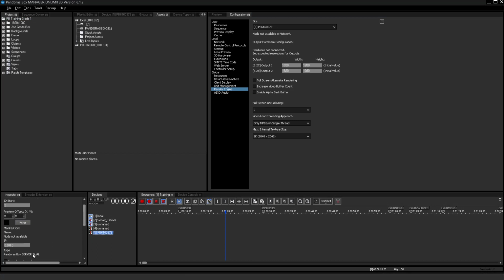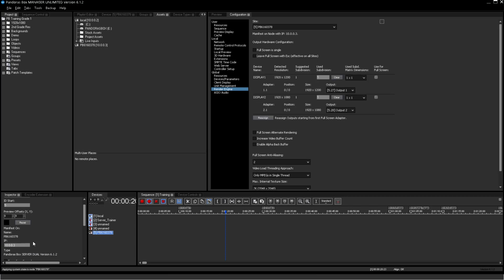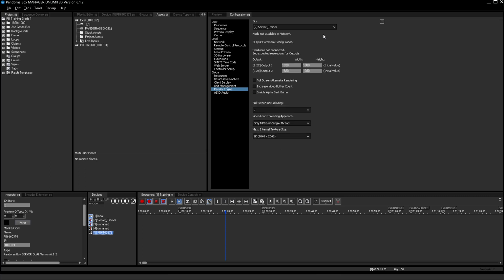After connecting a real site to your pre-programmed project, the incoming EDID of the client's output will replace the manually set resolution. If it differs from the setting used for pre-programming, positions and scalings may be inaccurate. For now, let's keep the setup simple and set all output resolutions to Full HD.